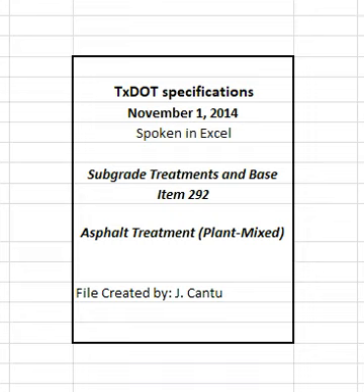3. Equipment. Provide machinery, tools, and equipment in accordance with item 320, equipment for asphalt concrete pavement. 4. Construction. Produce, haul, place, and compact the specified mixture in accordance with the requirements of this item.